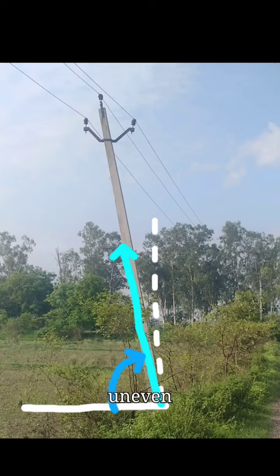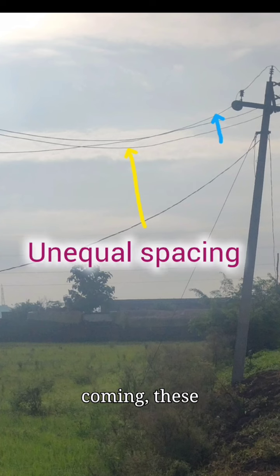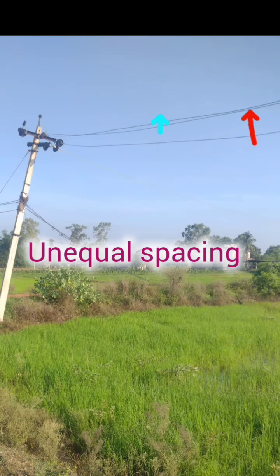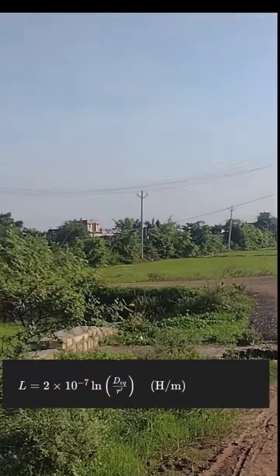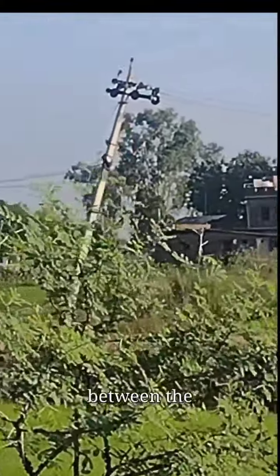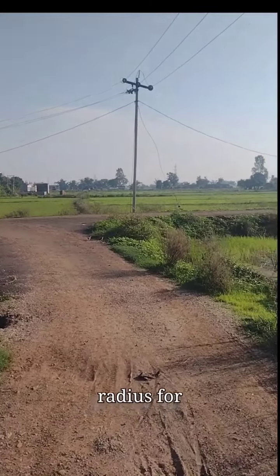Inductance per phase due to uneven spacing. As we can see, with these electrical poles, the three conductors have unequal spacing between them. Let's use the formula: L is equal to 2 into 10 to the power of minus 7 log D equivalent by R dash Henry per meter. Here D equivalent is the geometric mean distance between the conductors. R dash is equal to 0.01 meter, which is the effective conductor radius for ACSR.